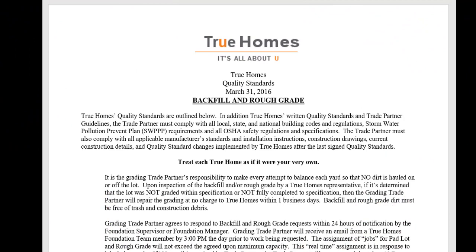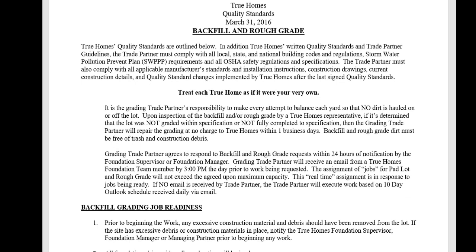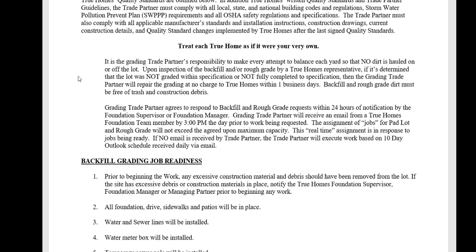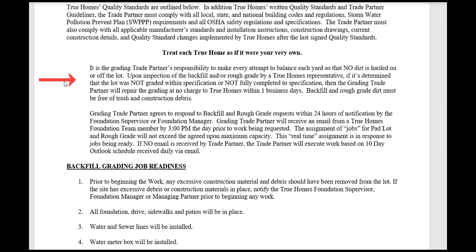Let's take a look at the backfill and rough grade quality standards and see what's pertinent to this quality check. Going down to this first bullet here, it is the grading trade partner's responsibility to make every attempt to balance each yard so that no dirt is hauled on or off the lot. Upon inspection of the backfill rough grade by a True Homes representative, if it's determined that the lot was not graded within the specification or not fully completed to specification, then the grading trade partner will repair the grade at no charge to True Homes within 1 business day. Backfill and rough grade dirt must be free of trash and construction debris.